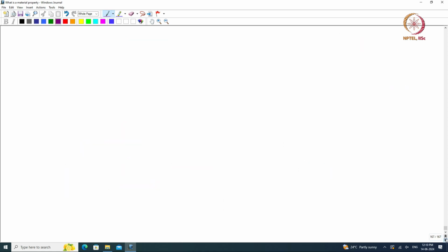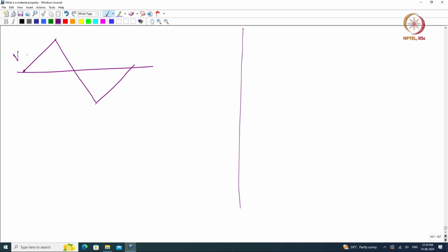So, the way I do this experiment, let me actually tell you that. I apply a voltage ramp like this, right. So, this is voltage as a function of time, and then I am measuring the current as a function of time, in a ferroelectric device.